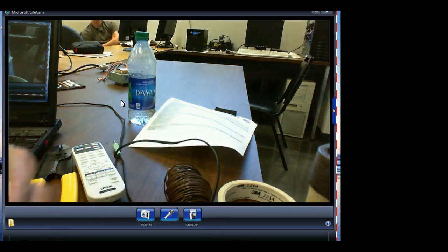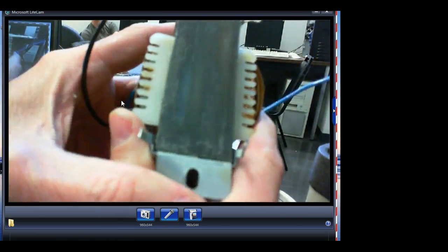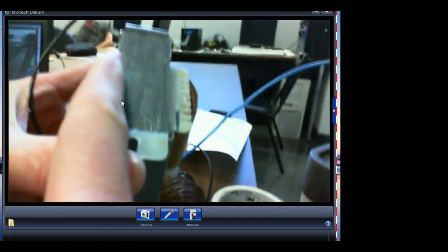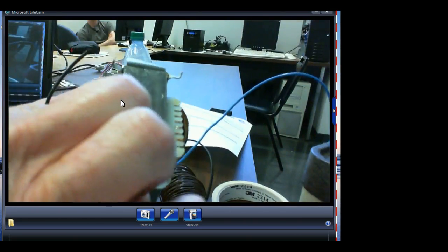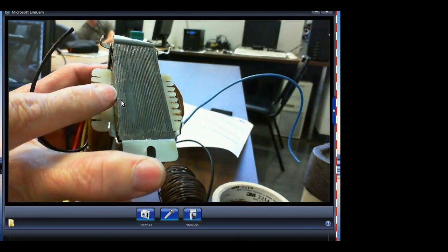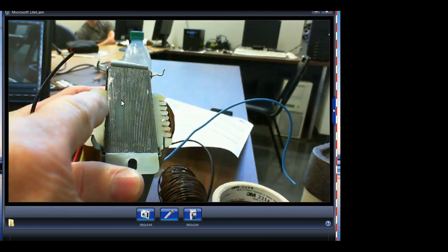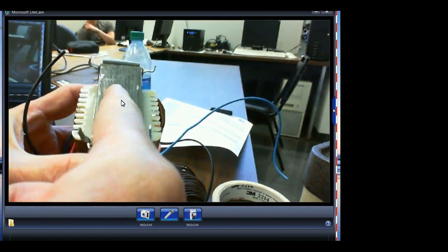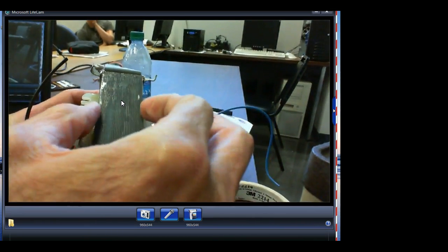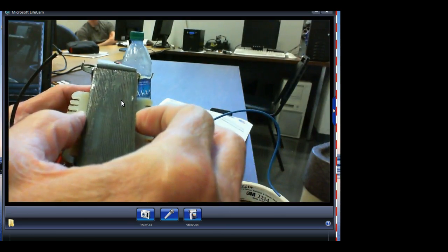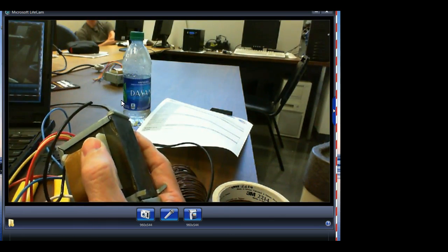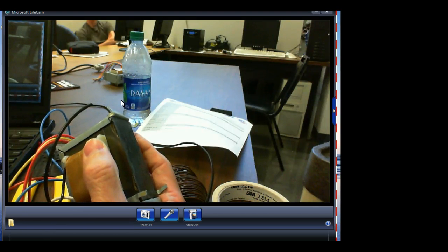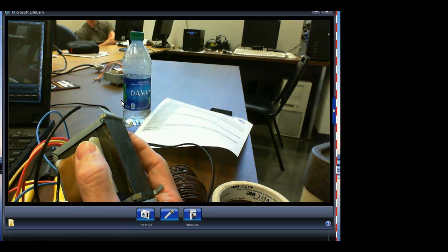So what they do is they divide it into hundreds of tiny plates, and they insulate the plates from each other. So that way the little currents, we call them eddy currents, that are induced in this plate do not combine with that one, and do not combine with that one. And it turns the core to be very, very efficient. So if you looked at an AC motor, you'd see that the poles that actually concentrate the field are what we call laminated. Does that make sense?